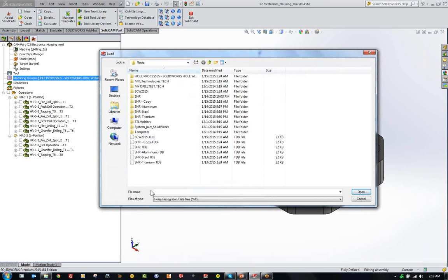So what gets installed with the system, you guys can very easily start to play with by simply dragging off a copy and going to play with that. Now you're not going to wipe out the system one. If you blow yours up, okay, you learned something. Throw it away, start over, make another copy, and continue. If you want to make a copy from one machine to another, or from one material to another, you can do that. Simply go in and change your feeds and speeds to accommodate that new material. Makes it very simple.